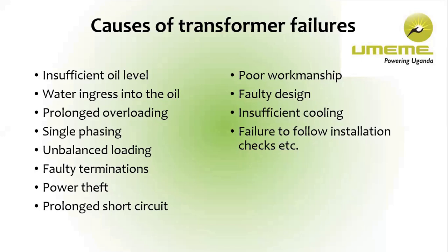Faulty terminations. Power theft, I've talked about those who will come and start tapping illegally on the line, and this can cause overloading of the transformer. A prolonged short circuit: there can be some short circuit inside that has not been identified, and with time this can cause problems.